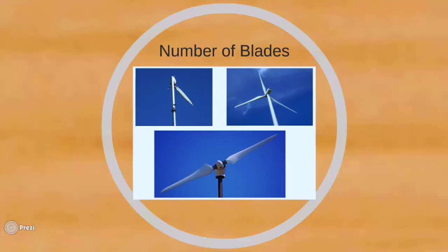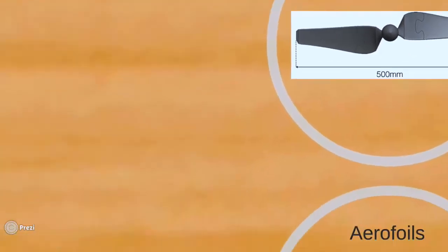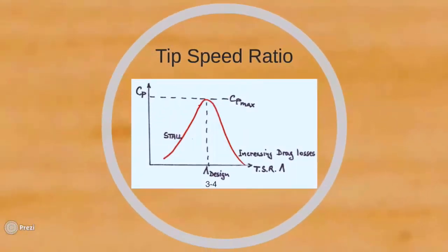However, more blades increases weight and induces more skin friction drag. 1 blade would reduce it, but the need for a counterweight for the turbine to remain stable makes it inefficient. The next best option is a 2-bladed turbine. Using the maximum diameter of 500 mm, more power can be extracted as a result of the maximum area being swept. According to this graph by Professor Graham, the maximum efficiency of small wind turbines is at tip-speed ratio between 3 to 4 without inducing high viscous losses.